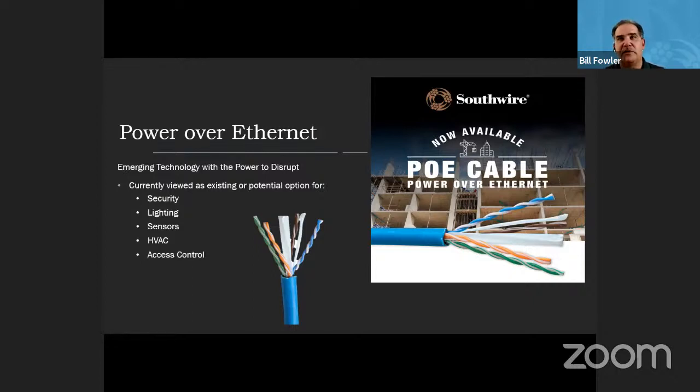Very, very important when you're dealing with higher speed is to keep those pairs consistent throughout the length of the cable. That helps on your crosstalk from cable to cable. And you'll see typically 23 gauge, it's a little bit larger, has a little more space inside to space those pairs from each other.